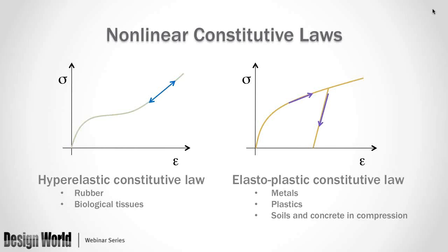Of course, in COMSOL, you can also add in your own user-defined constitutive laws, but these are two very common ones. Hyperelastic, obviously rubber, but biological tissues also often fall into this category. And elasto-plastic constitutive laws can handle metals and plastics. One very interesting aspect is soils and concrete in compression. We have found that a lot of users in the oil and gas industry have a lot of interest in how to model the mechanical behavior of soils and man-made structures like concrete. And so the elasto-plastic constitutive laws come into play there.